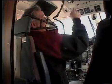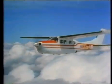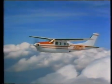Summing up, you must ensure that there is adequate oxygen flow and the proper percentage of oxygen is being received for the altitude you are flying to protect against hypoxia.